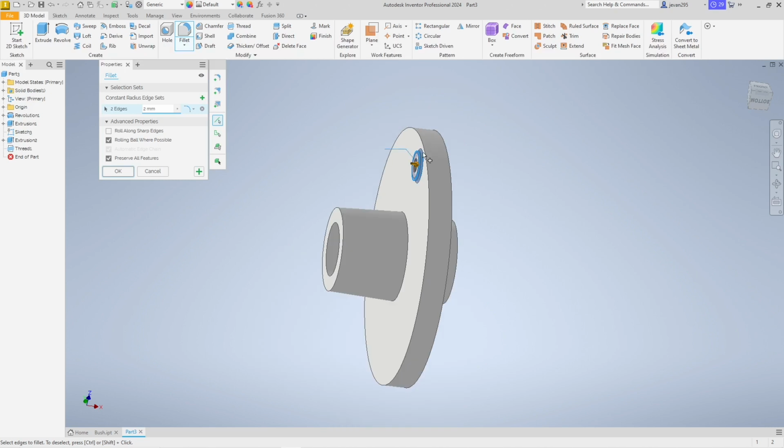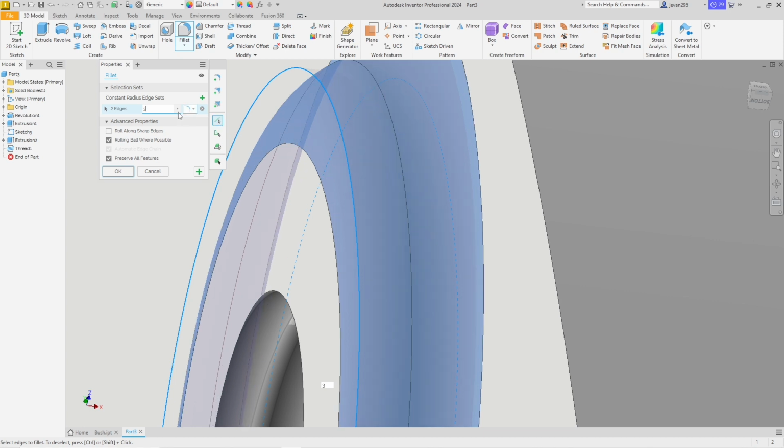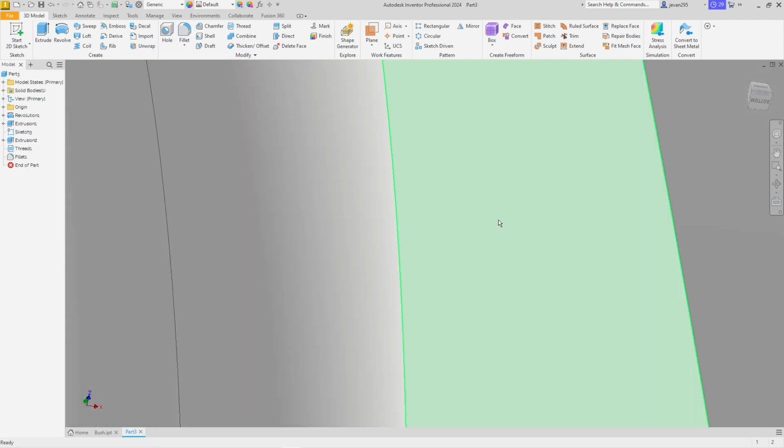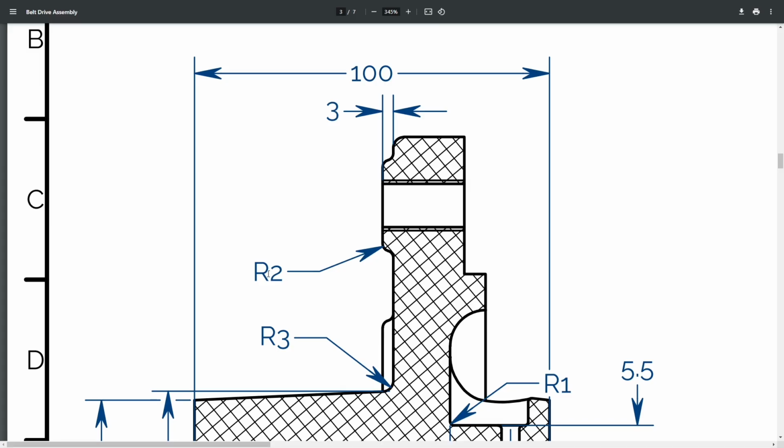Now, you could either do that as 2 millimeters, 3, whatever you decide. However, if we do it at 1.5, which is 3 over 2, it will create a perfect all the way across and all the way back. Just looks a bit nicer, but it doesn't really add a whole lot. So this R2, we're going to ignore that. We're going to go actually R1.5.